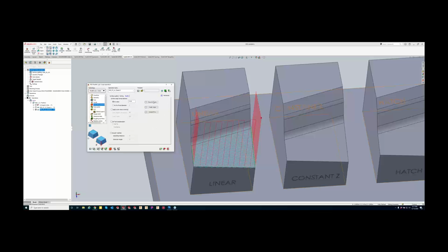But the one that you are going to use quite a bit is the extend trim. We can extend our toolpath beyond our certain area. If I wanted to extend my toolpath on the start, I'm going to go through each one of these here. For the start and end, I'm going to tell it I want it to extend by 100% of the tool.